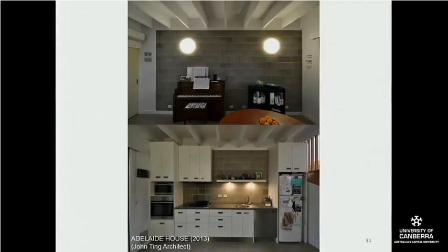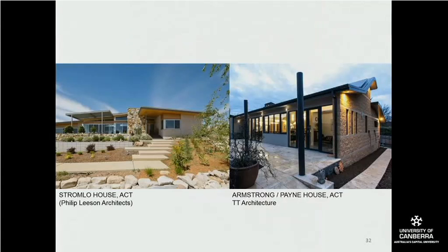This is an extension that I did in Adelaide, where we've used the blocks exposed. What we've done here is put a matte sealant over it, which makes it waterproof, so you can use it next to sinks, as the sealant will not allow water to seep into it. And then, of course, locally, these are two award-winning houses by local Canberra architects, where we see different uses of concrete block.